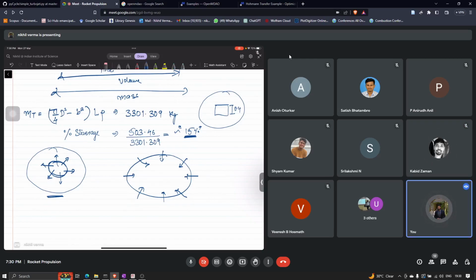From the outward towards the inward, and even the radially outward propagating burning grain is practically in use, because as you cross a certain altitude, your drag reduces and you want to accelerate faster. After some time, the pressure will increase and therefore the thrust will also increase. So they are commonly used.